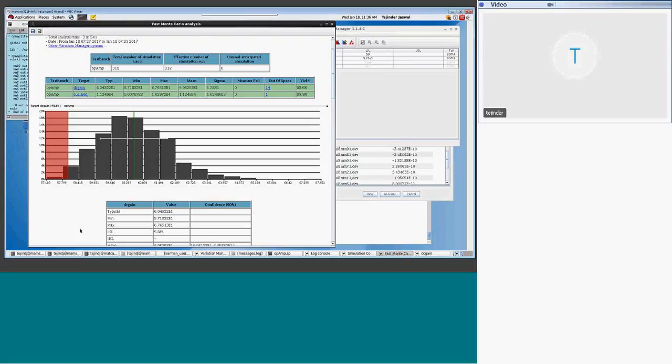Here, what you get in this report is only your output statistical distribution based on your Monte Carlo analysis. It will indicate the mean, max, min, and sigma. This really corresponds to the statistical distribution of each measurement of your design. For gain, for output frequency, you have mean, max, min, and sigma. And the out of spec, because we indicated the LSL, just forget it.